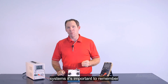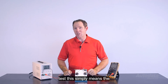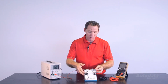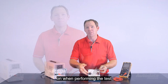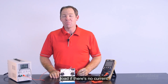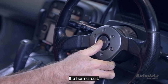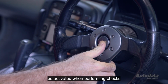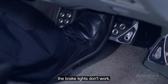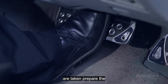It's important to remember that a voltage drop check is a dynamic circuit resistance test. This simply means the circuit needs to be switched on when performing the test. Remember, there'll be no voltage drop across the load if there's no current flowing. If we're testing the horn circuit, the horn needs to be activated when performing checks and measurements. Or if the brake lights don't work, the brake pedal must be depressed before any measurements are taken.